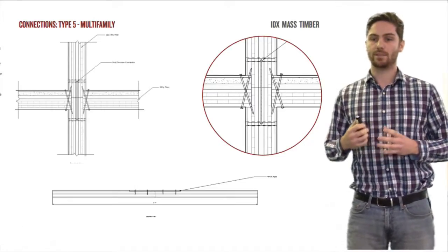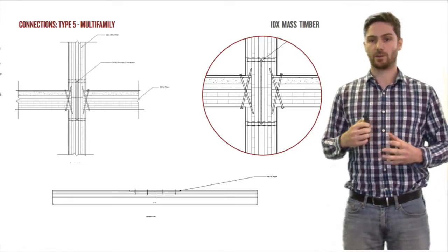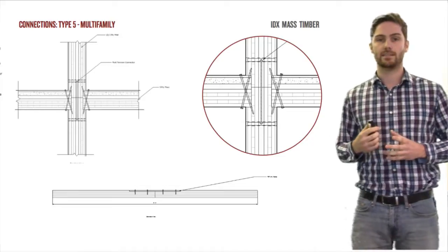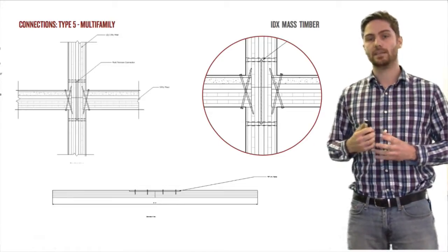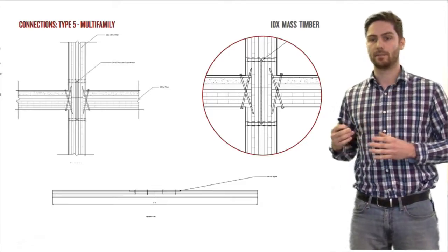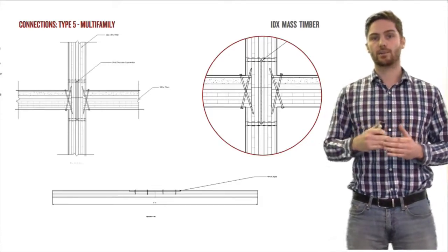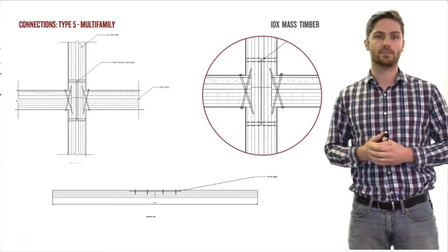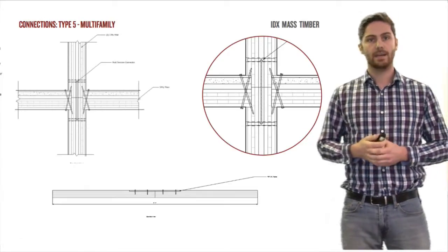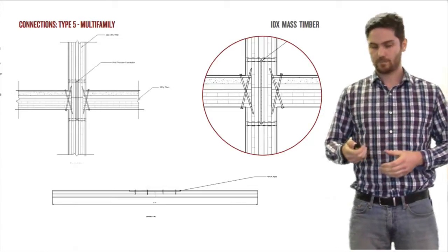What it was, the vibrations that would occur in the CLT. And so what we had to do for all of our building types, some a little bit differently than others, was add concrete on top of this to get composite action in order to span these lengths appropriately to avoid issues of vibration or deflection and other issues as well.